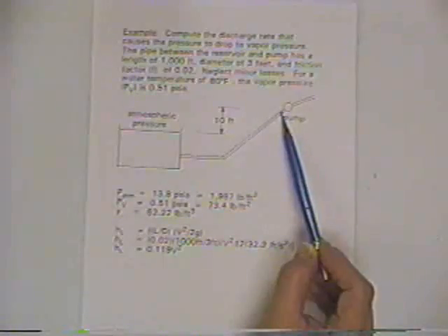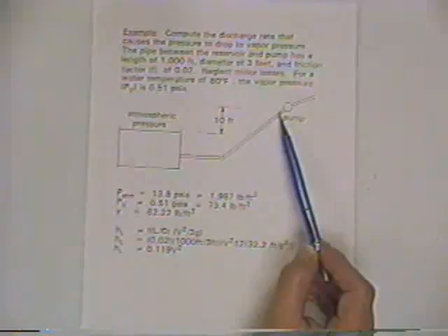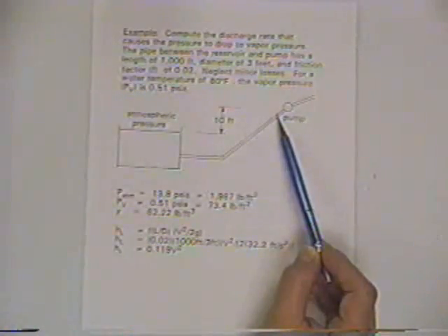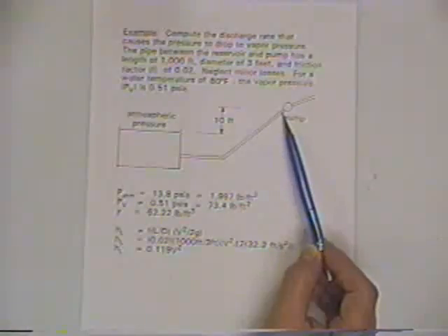And if we drop the pressure low enough, of course, there's a limit. You can't drop it any more than atmospheric pressure, because you'd be down to absolute zero. But even before you get to absolute zero, practically what happens if you get down to vapor pressure is that the liquid water starts making bubbles of gaseous vapor. And then those bubbles can implode, and a problem called cavitation occurs. You can actually do destruction to the pipe and to the pumping system and so forth.